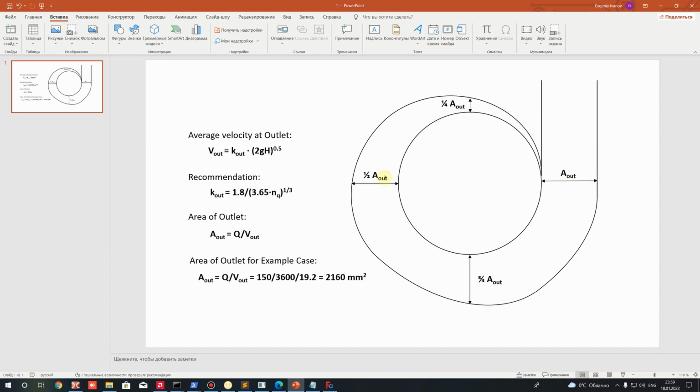Here we will be using the box approach when we create the 2D sketch of the volute in FreeCAD and just extrude this CFD domain for the future CFD simulation and merge it with our impeller.